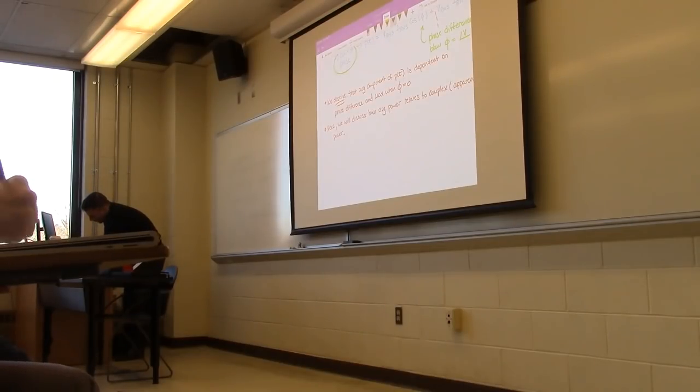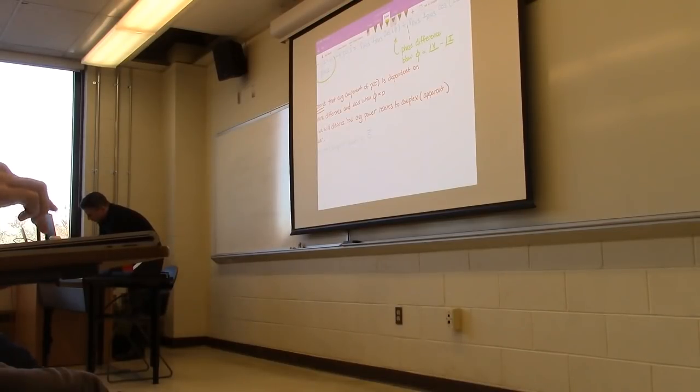So apparent power, is it two P's? Yeah, it is. Apparent power. Also we'll use the term complex power, is equal to, so we'll represent it by the letter S, and it's equal to voltage times current conjugate.